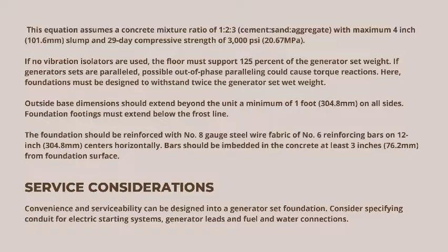This equation assumes a concrete mixture ratio of cement, sand, and aggregate with maximum 4-inch slump and 28-day compressive strength of 3000 psi or 20.67 megapascal.